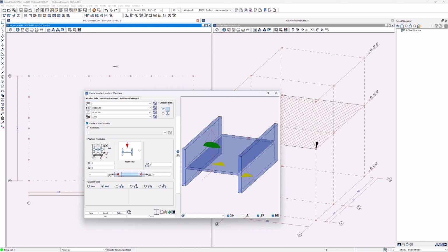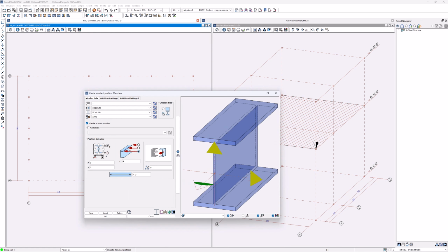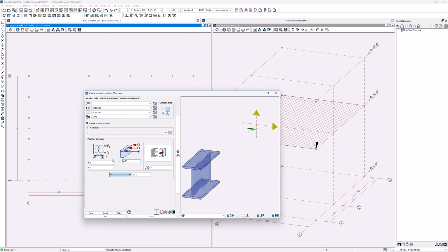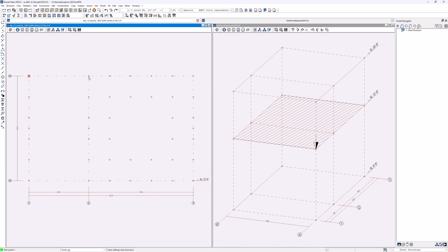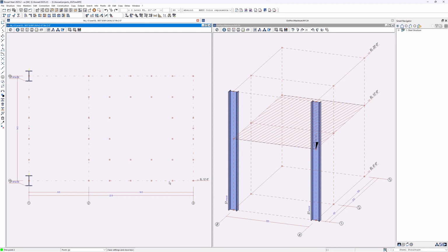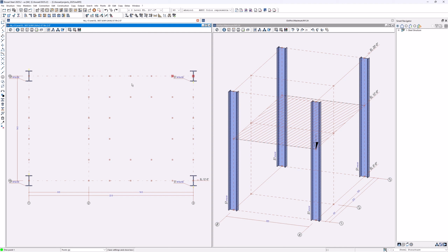Over here in that 2D view, that top view, creating the columns like this will not be possible. So I will go to the perpendicular view. Total length of the column is 20 feet. We'll place it down, but we have to do 20 minus the 12. So I'm going to say 8 feet pulled up. 1, 2. There's the column. 1, 2. There's the other one. 1, 2. 1, 2. Same thing over here and there.